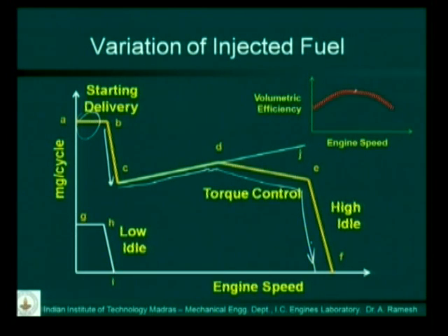This is speed-based control. So far we have seen only injection, but now it is speed-based control. The injection controller has to control the quantity that is injected based on speed. At this speed, it has to permit this much quantity. At this speed, it has to permit a lower quantity. Again, a lower quantity, and very, very low quantities here. So with respect to speed, it has to continuously monitor the quantity. With respect to load and speed, it has to monitor injection timing. It has to decide the number of pulses. All this, and the driver doesn't know any of this. The driver only presses the accelerator.